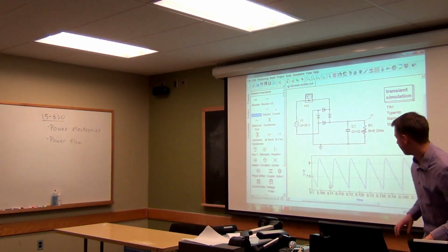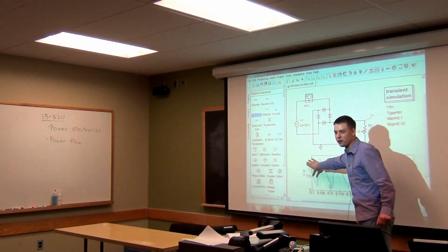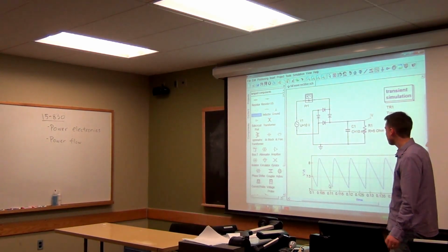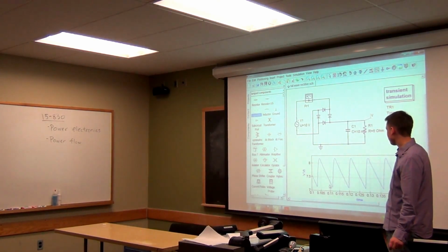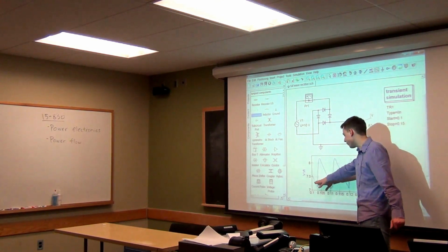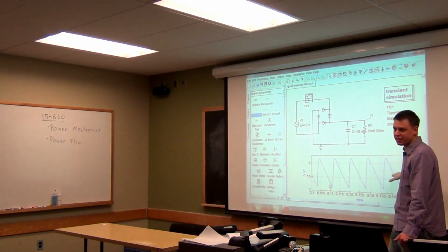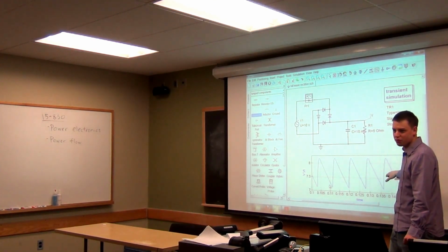So what we see here is actually the axis is scaled differently now, but it's only showing us the bit here that after this is settled in. But what's happening here is that by adding this capacitor, we have made this voltage more or less a constant DC source. Sorry, does this make sense?